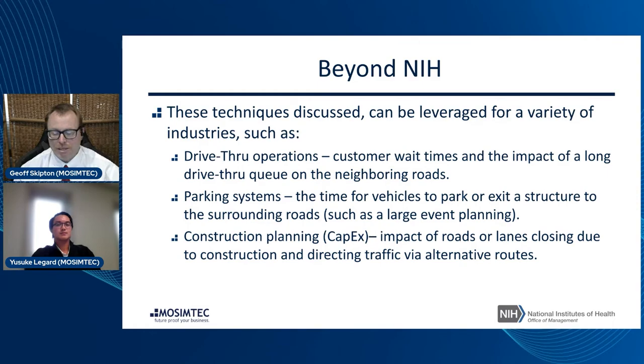I do want to note that we've used the road traffic library out of the box, and it is wonderful, but we use the stop lines, and then I particularly just manipulate the car. So when a car goes across the stop line, I can see where they're at, and I can see if they're at a window, for example, to get food or to make a payment, or if it's outside service, they're next to somebody that's trying to take an order. And then we just trick the car by setting its preferred speed to 0. It stops the car and then throws us a nice event that says, hey, I'm stopped, I need service. Once the service is complete, we can just set the car's preferred speed back to 5 miles per hour or whatever it happens to be, and the car can move on.